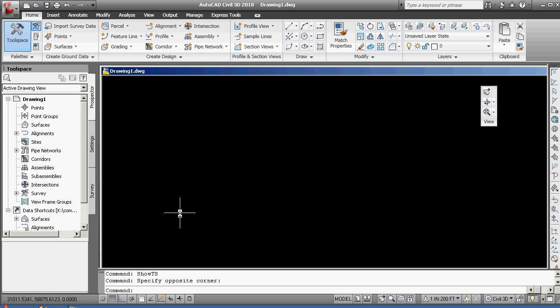K drive. You needed to go through and map a location on your network or in the cloud to the K drive, and from there you then proceed into Civil 3D. You will then, and you always need to be aware of using visual clues to make sure that your environment is set right. We are going to use the black space for the visual clue of us being set up